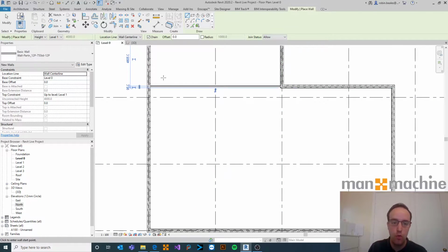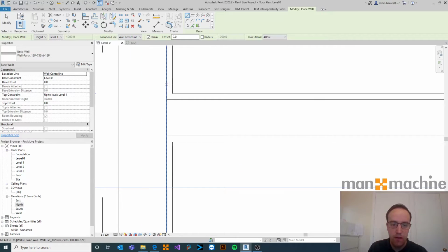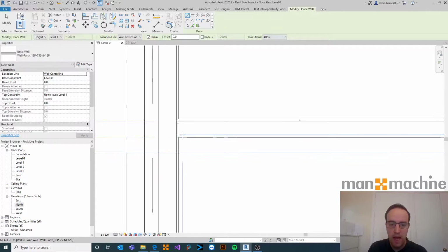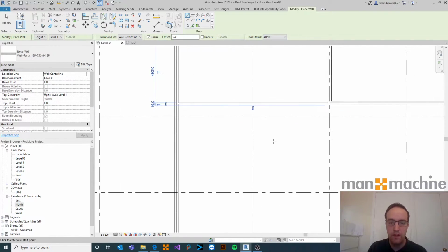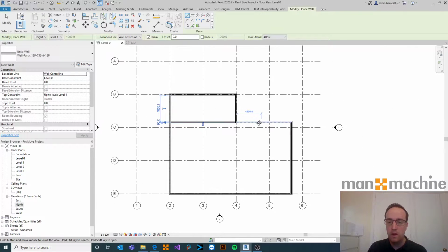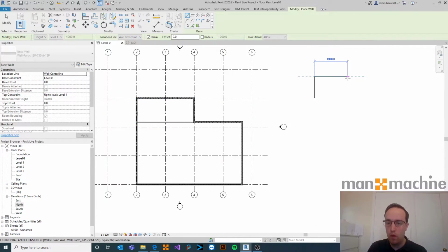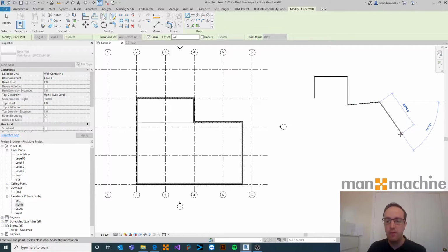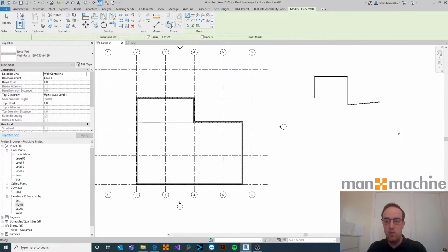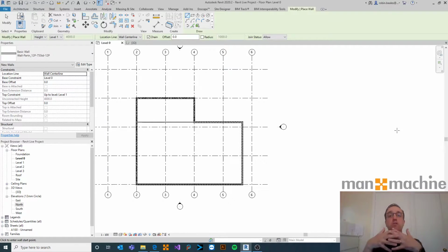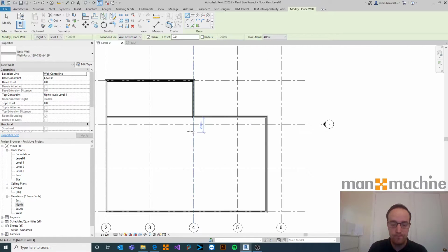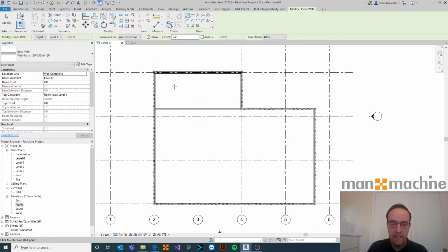Because we've connected two walls together there, you'll notice that it wraps the plasterboard, and it also comes out of the chain of walls, if you like. You know, if I was drawing wall after wall after wall and they're not connected, it would keep drawing. But the second that you make that connection of one wall to another, it will stop that chain because it knows that you've connected those walls up. So we have this area here, which we'll say is our reception area.